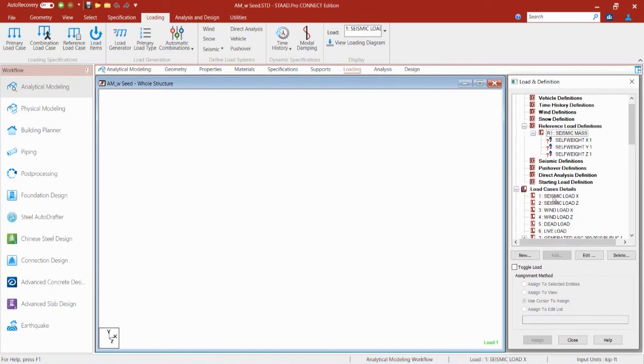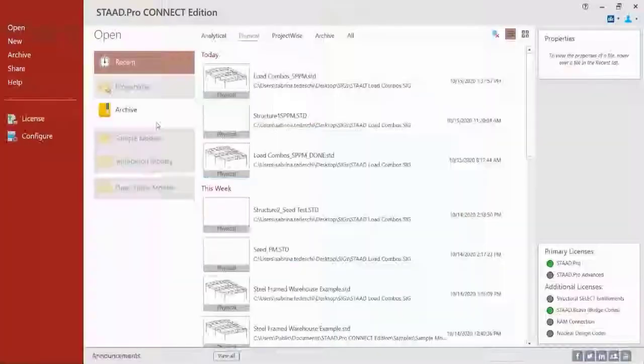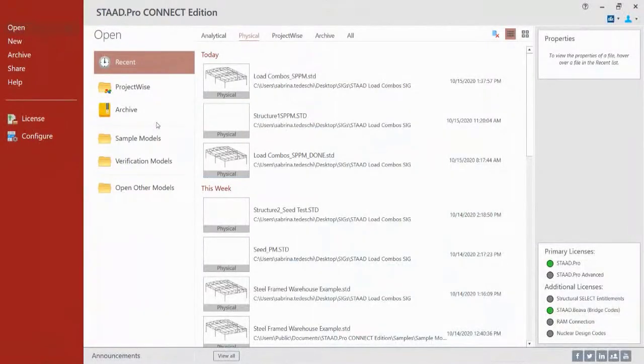If you're doing a model that has seismic loads with, say, orthogonal effects, where you have multiple permutations of load that maybe you use often, you can now create seed files, which I think is a huge advantage for you. I know in the past I've had sample models with common loads that I used before, and I usually just copy them and paste them in my input file. And now we can do that automatically when you create a new model. Again, available in update 5. Now you can do that for the analytical model.